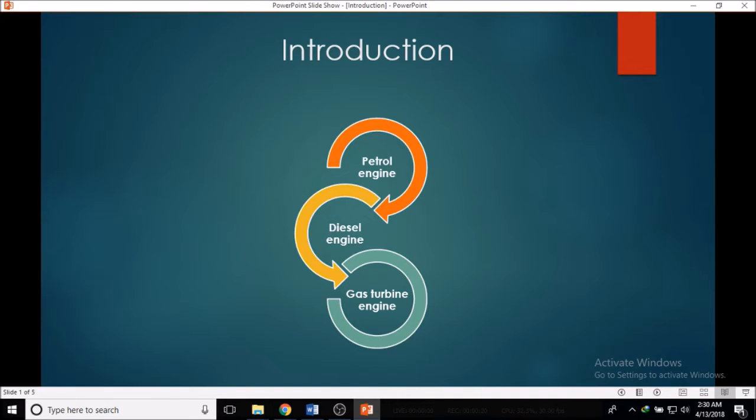For the introduction, what we discuss is the gas turbine engine. The basic operation of the gas turbine is a Brayton cycle with air as the working fluid. Fresh atmospheric air flows through the compressor that brings it to higher pressure. Energy is then added by spraying fuel into the air and igniting it, so the combustion generates a high temperature flow.